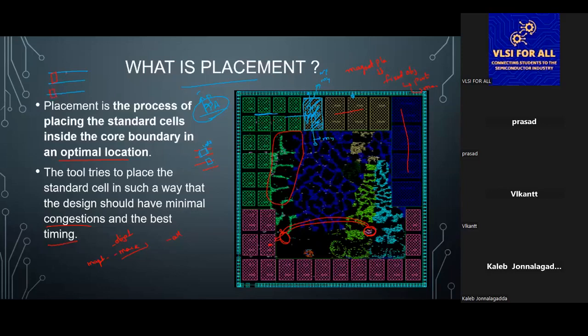But in the macro's case, if I can place it like this, okay, this is a macro, right? So it is legal only. So what I can do here, no cell is going to sit. Okay, I have ports here. So if it is here like this, there is no cell going to sit. Is it legal, and is it an advantage or disadvantage? If you want to comment. So it is some kind of advantage only, because no other standard cell will sit in this area. So it will sit here only. So this area you can use for routing resources, for routing purposes.